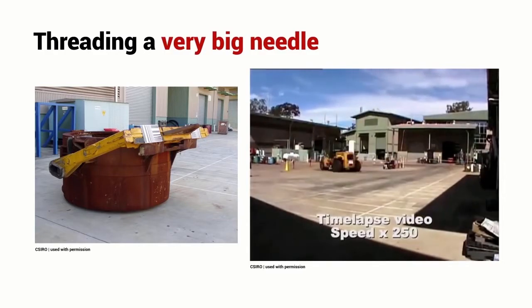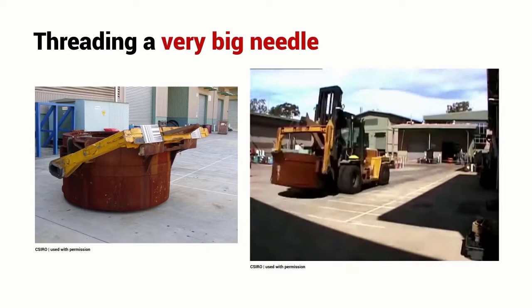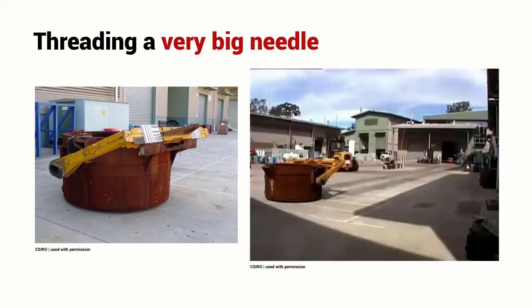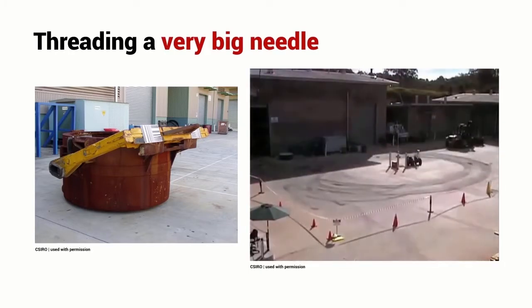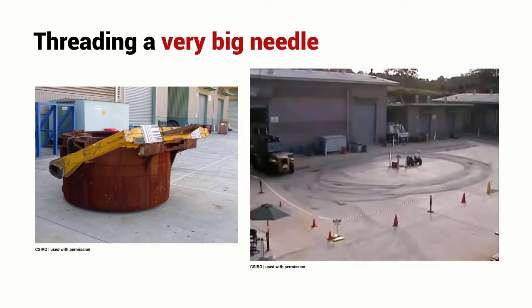What you see now is a time-lapse movie. We ran this experiment over a whole day. Over the course of the day, the lighting conditions changed, clouds came and went, shadows came and went, but it showed the overall robustness and reliability of this vision-based strategy. The robot didn't have any knowledge of where the crucible was, it just moved to reduce the error between the tip of the hook and the handle.